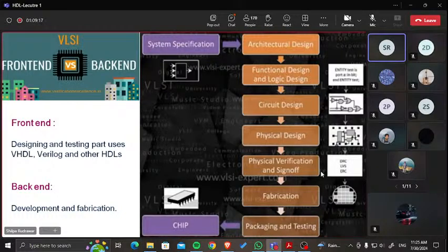So here, if I am saying that I want to implement an AND gate with inputs A and B, just see on the screen, I am just rotating my cursor: this is A, this is B, this is C. So my design should be near these. Where should I place the design, which is preferable, here or here? Here, isn't it? Because if I implement it there, unnecessary routing delay will be more, and that's why that thing will be taken care of by your EDA tool. You need not take care. Clear?